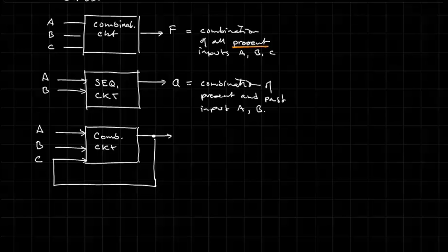It's basically this feedback that says whatever state the output goes to now becomes a logic level that goes back to the input, and we might latch the output to a particular state such that it remains at that logic level even if the inputs A and B should change.